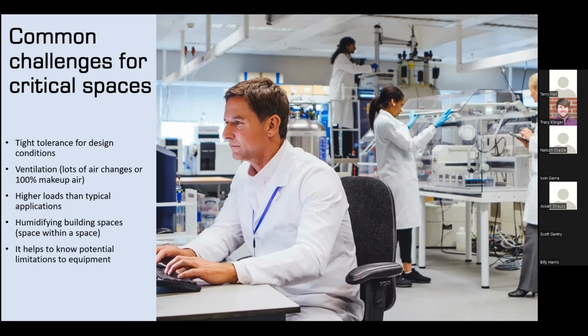Other challenges if you're humidifying a space. So what I mean is a space within a space. If it's a common air handler, but you want to humidify just one room, if it's a computer room or something, you're going to have the challenge of losing your moisture through the return air into other parts of the building, and so you're going to have to size for that accordingly. And in those cases, if there's a critical application, it's recommended that you really isolate the space on its own air handler.